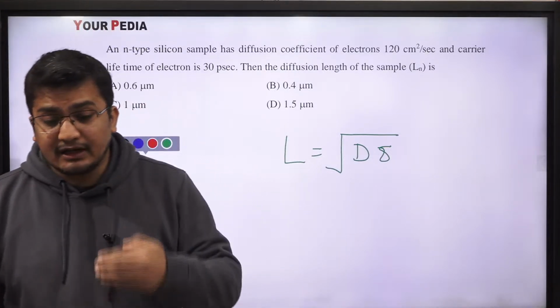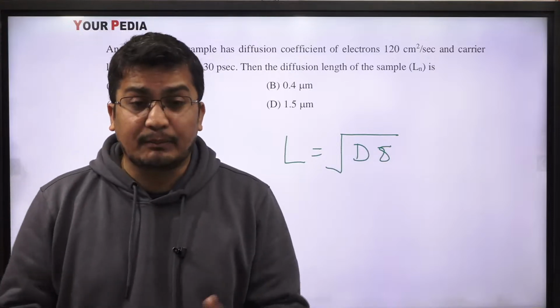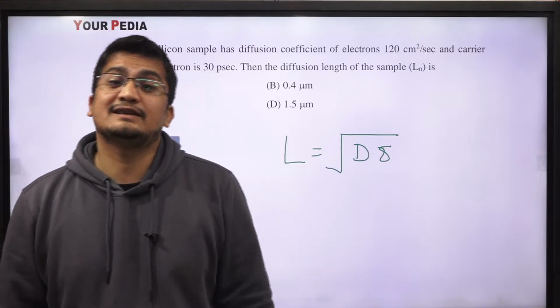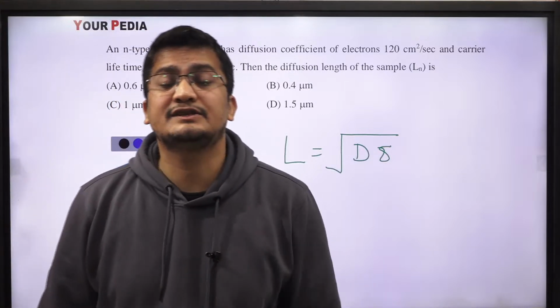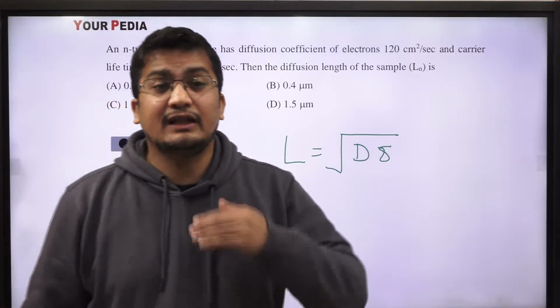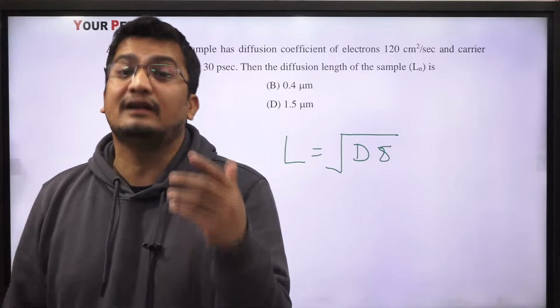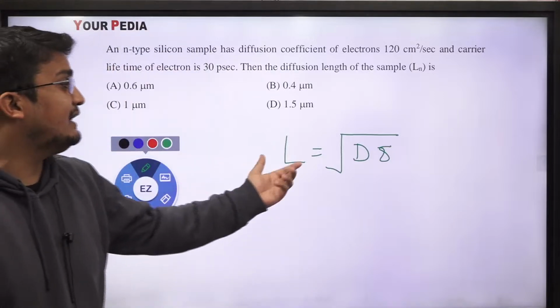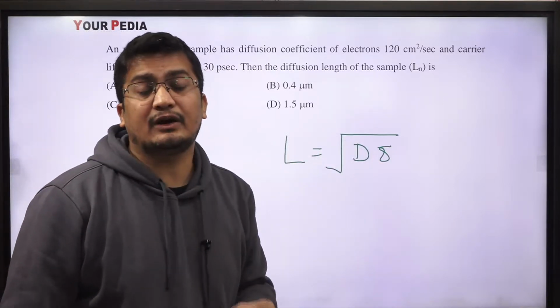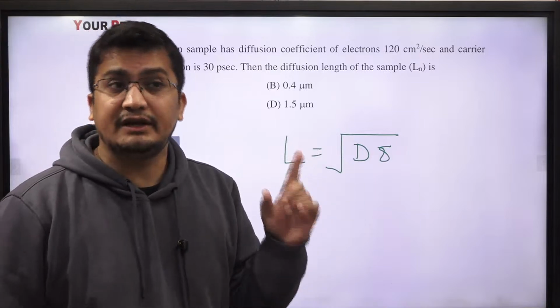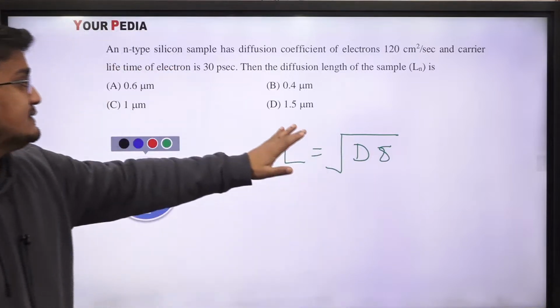As the charged particles progress in the specimen, when both polarities are there, the chances are that recombination will occur and the charged particle may disappear. So the length up to which it can survive needs some parameter, and that is the diffusion length. It is defined as L equal to under root of D tau, a very important electronic device relation we have derived in EDC. Is it clear? So you will be using this relation.